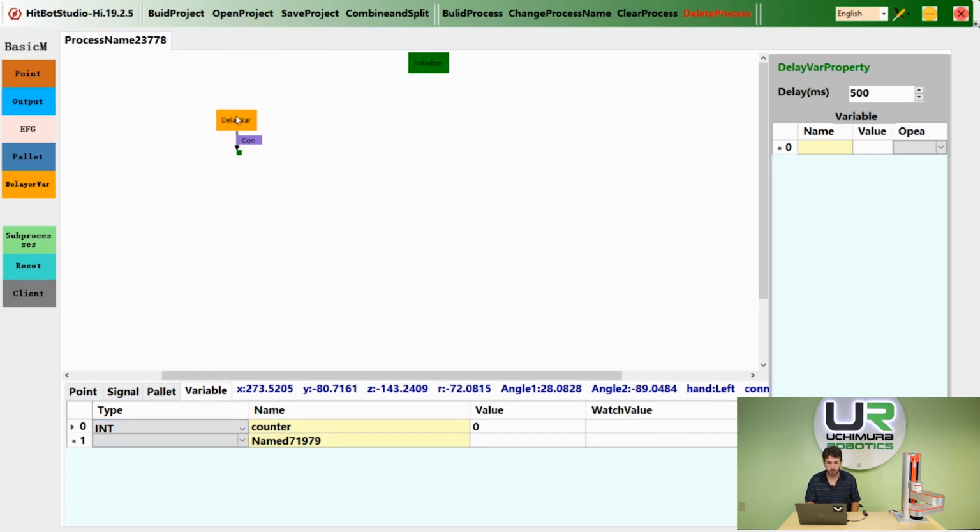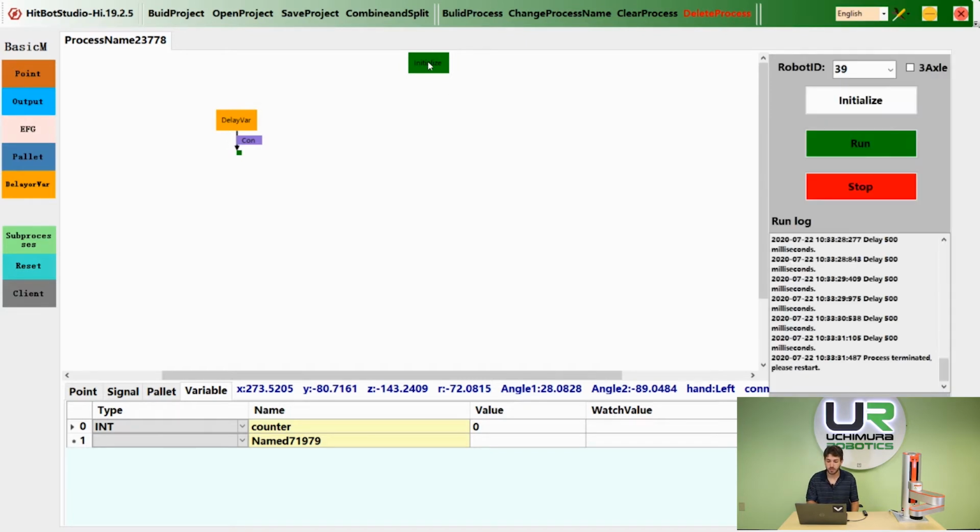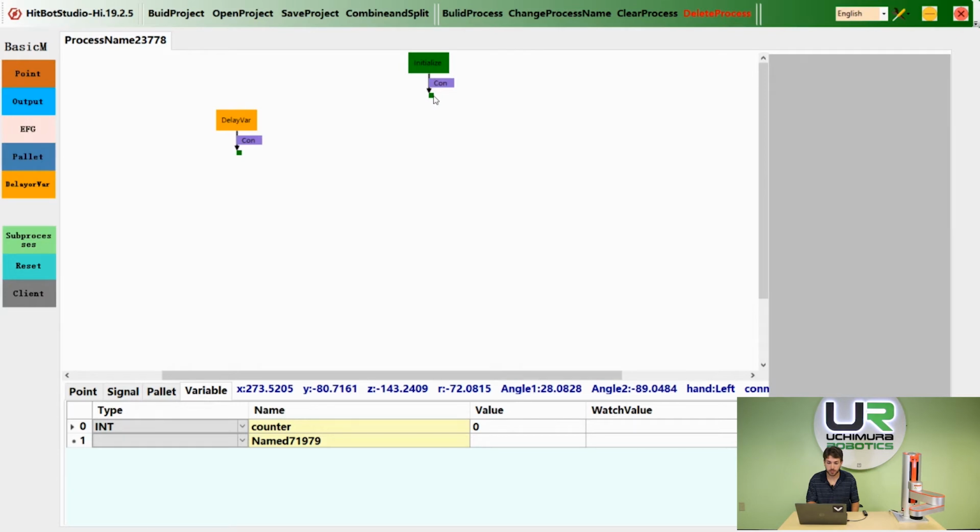Once you've created your variable, right-click on the node, and it should show up. If you have multiple, you can choose. Give it an initial value and an operation. For ints, you can do a +1 or a -1. It can be an int, then click Save Var, float, or bool. If we run this program, the value should update every half second.